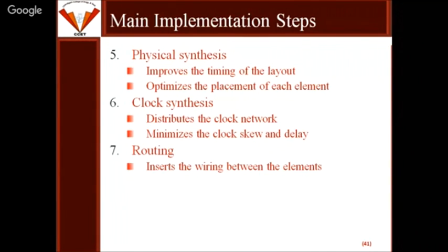Then the point comes how we interconnect those two devices so that the clock will reach them within the same time. Somewhere the clock generator is there. We also create some clock distribution points in the chip. So many distribution points will be there, and we have to connect to the different distribution points such that the synchronous event will start at the same time.